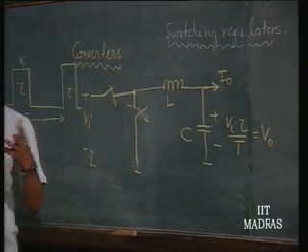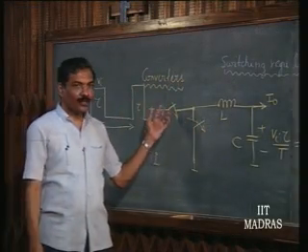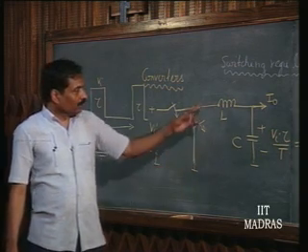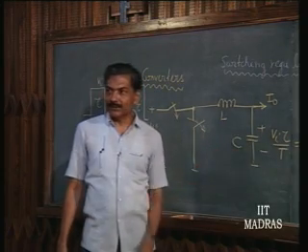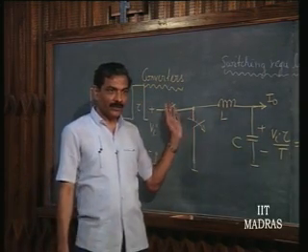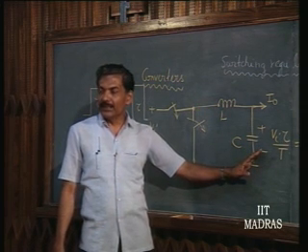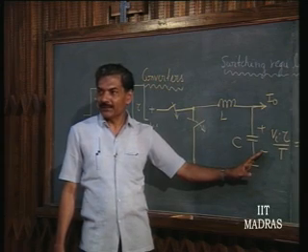These switches are going to be active switches, in the sense they are going to be MOSFETs or transistors. Inductor, ideal inductor, 0 dissipation, ideal capacitor, 0 dissipation. The places where dissipations occur, you have to keep note of, so as to see how close it is going to be to 100% efficiency.